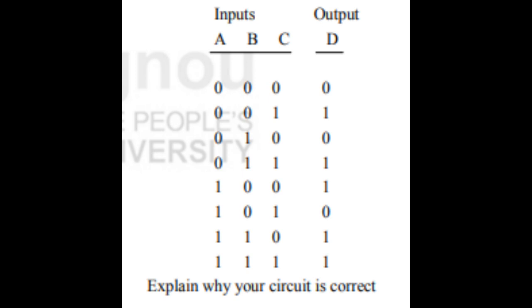14. Design a logical circuit that will calculate the less than function for 2-bit inputs. That is, if the inputs are A and B, each of whose values can be in the range 0 to 3, i.e. 00 to 11 in binary, then the output should be 1 whenever A is less than B.